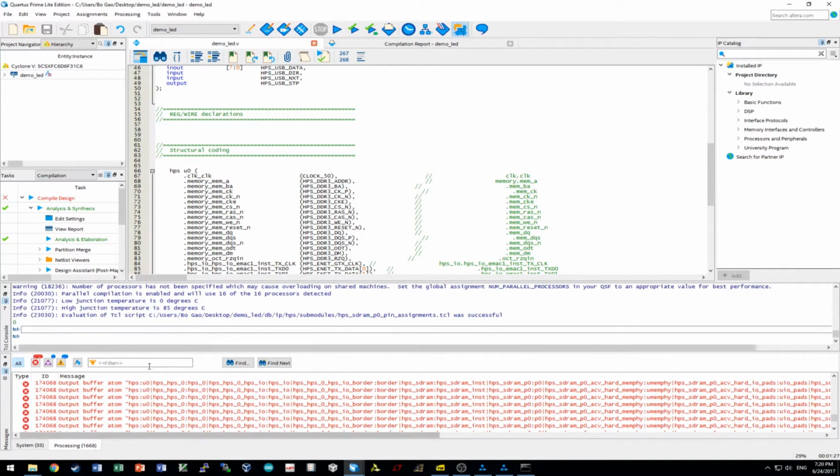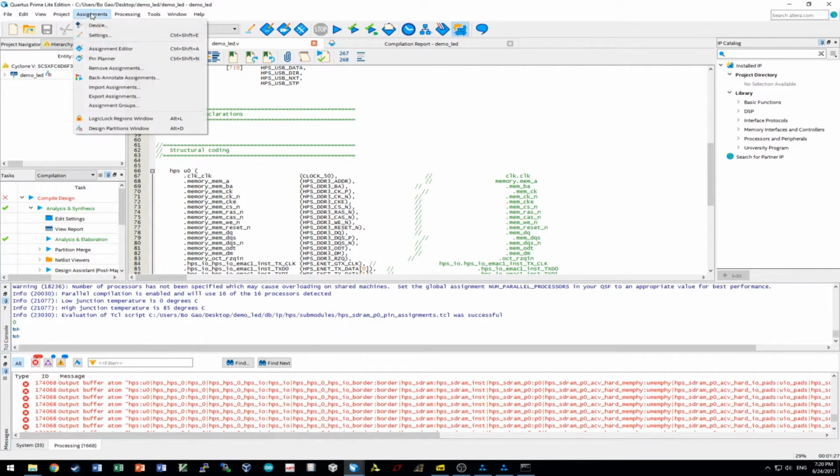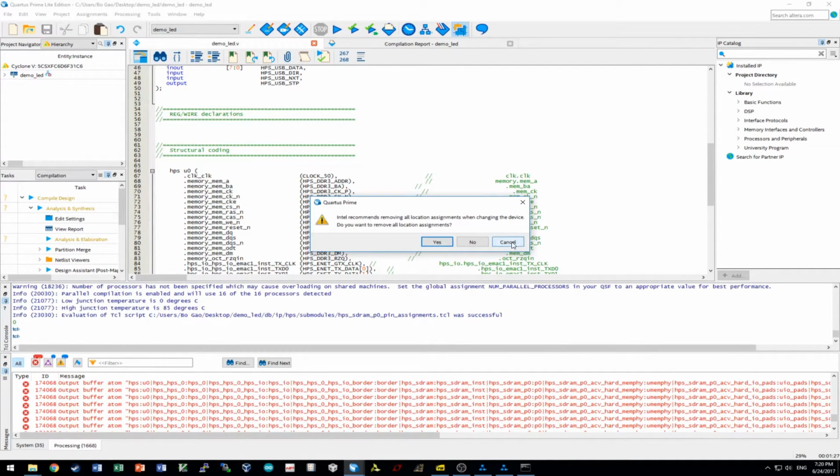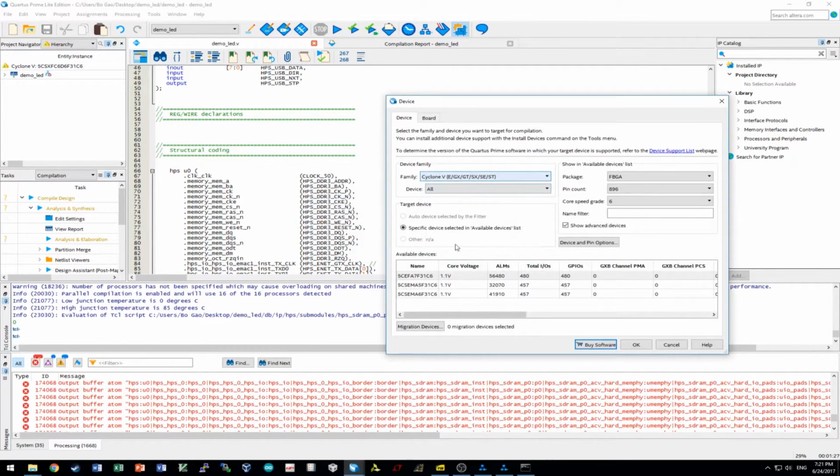Okay. So now we can do the synthesis once again, but before we do that, let's do this. Here, beware, be very careful. That's a bug of Quartus. When you try to assign the default pin behavior, I want to change them from pull up to tri-state without any pull-up resistors. To do that, you have to go to Assignments, Device, and there will be a button that says Device and Pin Options. But if you use the design generated by System Builder, it will automatically reset the device to the default device. So that's the trouble.